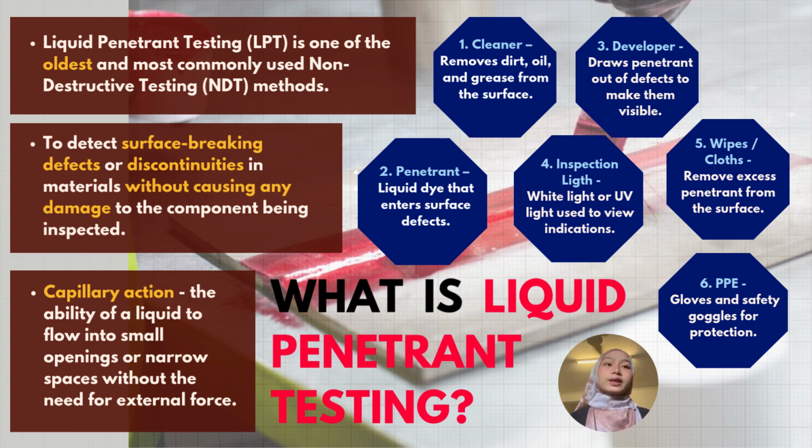First, clean the surface. Next, apply the penetrant dye and let it dwell. Wash away the excess surface dye, apply a white developer to draw out the trapped liquid. Inspect the visible indication and finally post-clean the part. For on-site inspection or field work, technicians use a portable 3-can aerosol kit. This includes a solvent cleaner, the penetrant dye, which can be a bright visible red, or a glowing fluorescent dye, and a spray-on white developer.